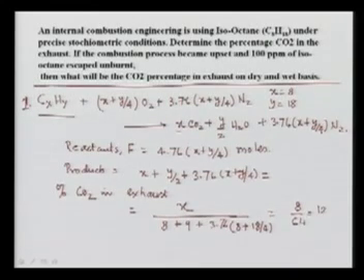So that is 12.5% of CO2 in exhaust. That is my answer to this problem: determine the percentage CO2 in the exhaust. I repeat, I wrote the general combustion reaction equation, balanced it, and then found the product side. Product is x moles of CO2, y by 2 moles of water, 3.76 x plus y by 4 moles of nitrogen.